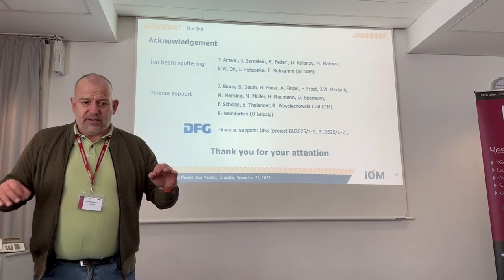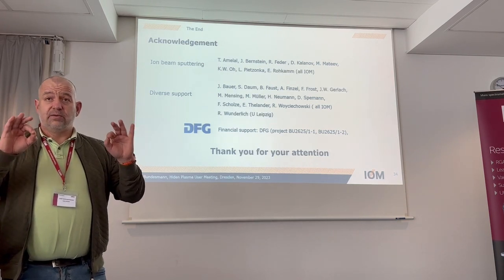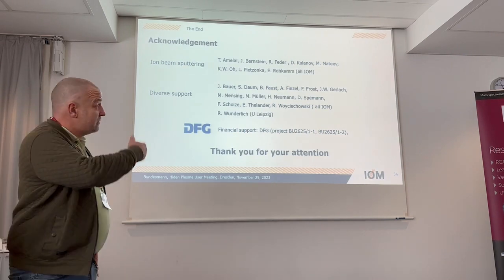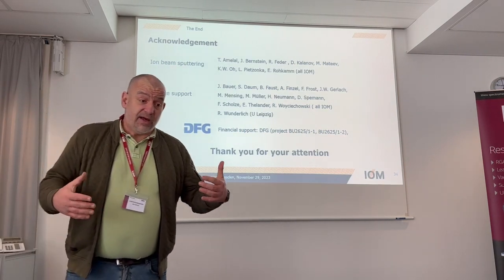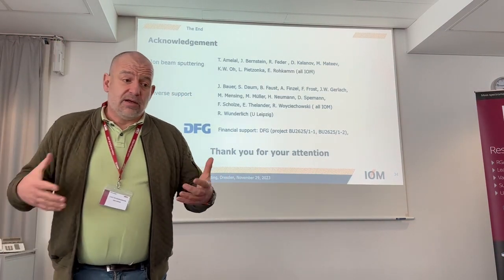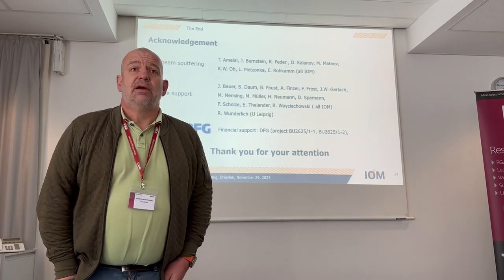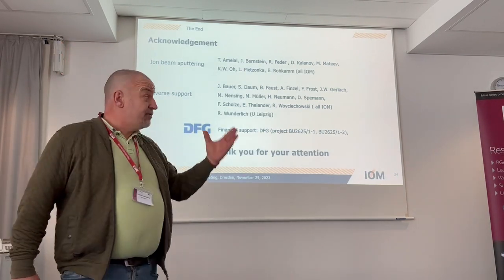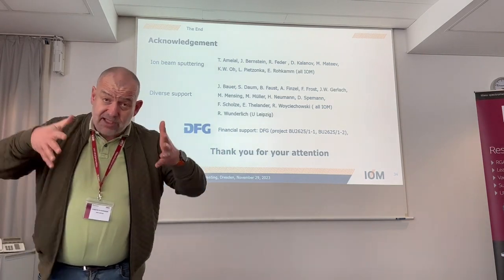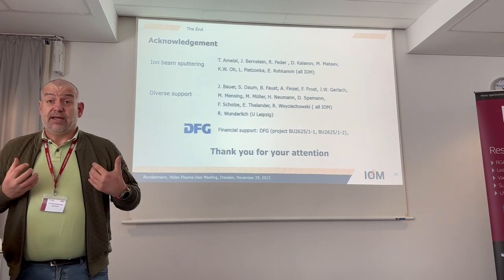I always say the systematics is nice, and this is true. Quantitatively, it's probably not that easy. You also cannot use these numbers from the composition, because if you have energetic particles hitting a surface, then normally primary particles, the noble gases, are just outgassing. But we have here a certain number, up to 10%. That means they must have a certain energy in order to get deeper into the growing film, in order to be able to stay there, not to get out again.